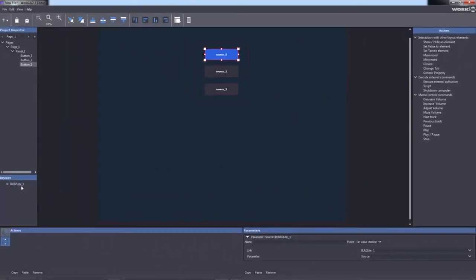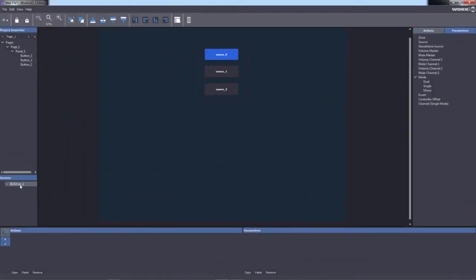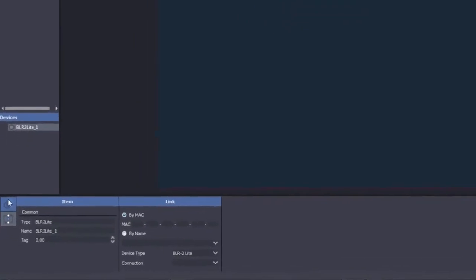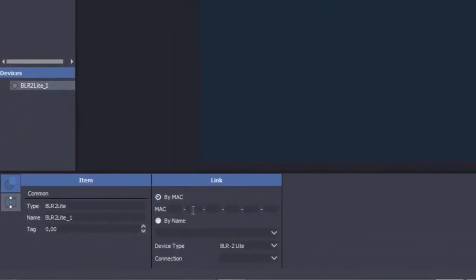We should link the device to our network, and for doing this we click on it in the Configuration tab, either through MAC or by the name. We would link the device to the network and we will choose UDP type connection.